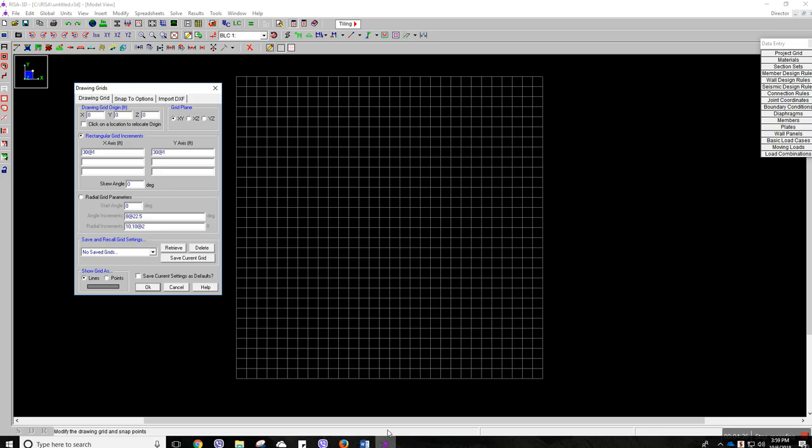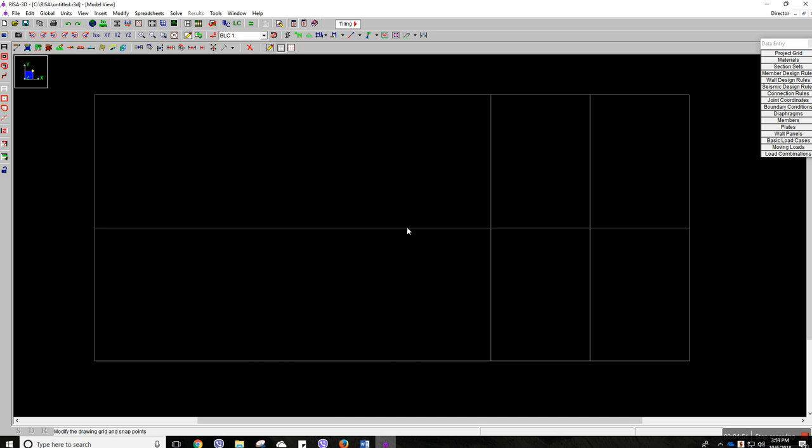So let's divide here. This is the x-axis, so one span at 44, and two more spans at 11, and you can just use a comma there. For the y-axis, we already know there are two stories, and each one is 15. When you do this, just click OK. Your grid will change to look like this. So this is our x-y axis of the building. Before drawing any structure, we need to assign the section sets for it, like this one, which is steel.